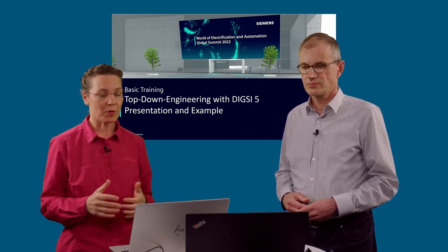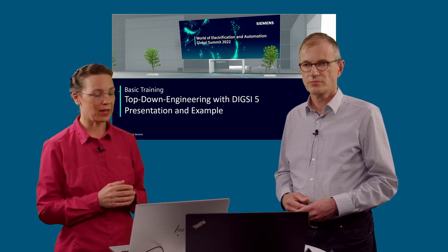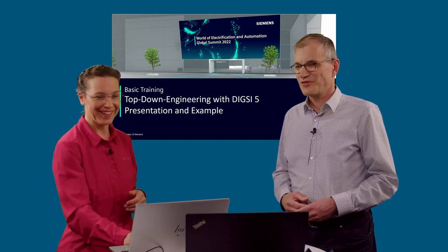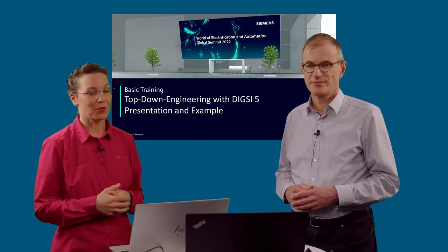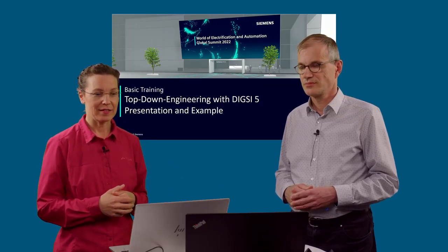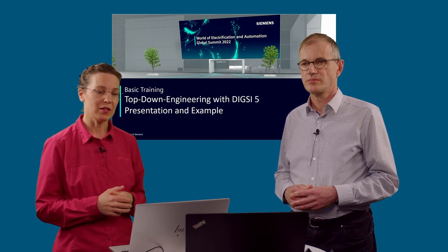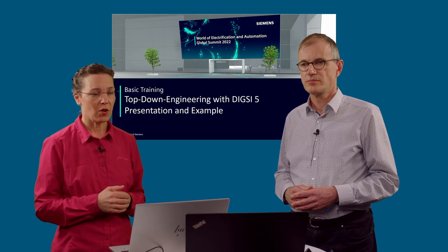So can DIGSI perform validation of the SCD file in accordance with IEC 61850? Yes, it will. If it finds something, you for sure will get in the logbox a message if something is wrong. Okay. And then does Siemens plan to implement the capacity to create SSDs with generic IEDs on DIGSI 5?